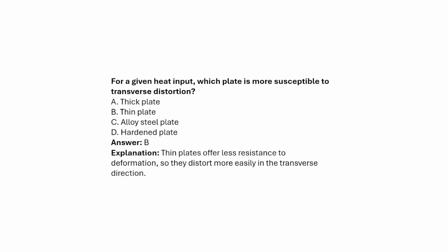For a given heat input, which plate is more susceptible in the transverse direction? It is the thick plate, thin plate, elastic plate, or hardened plate. The option will be thin plates, because thin plates often have less resistance to deformation, so they distort more easily in the transverse direction.